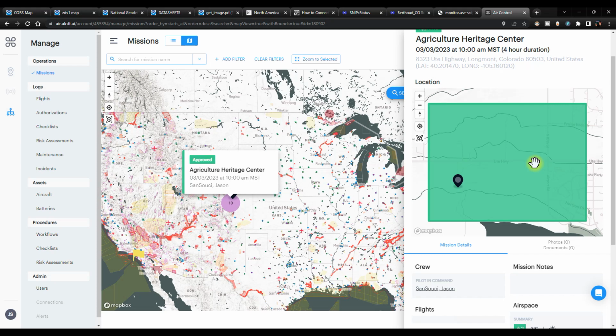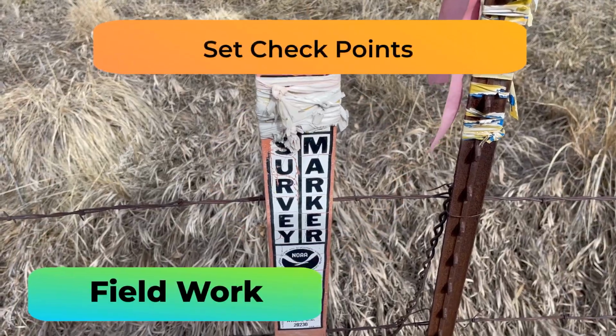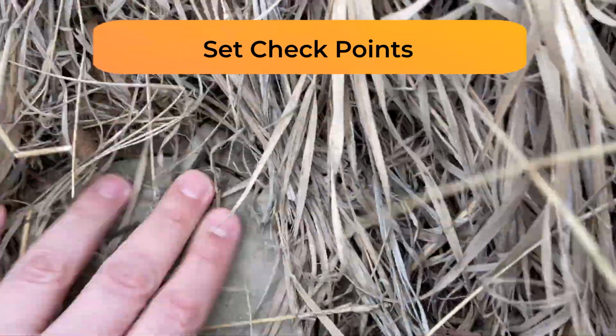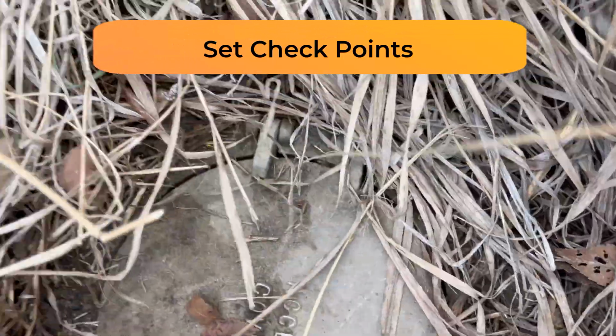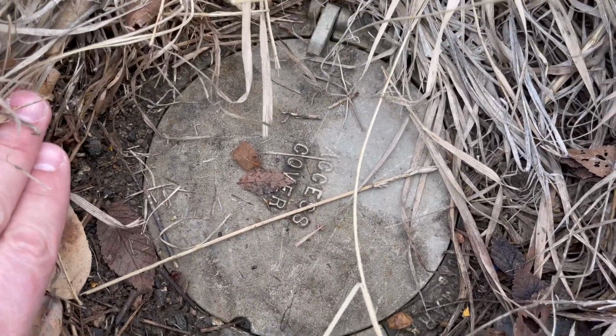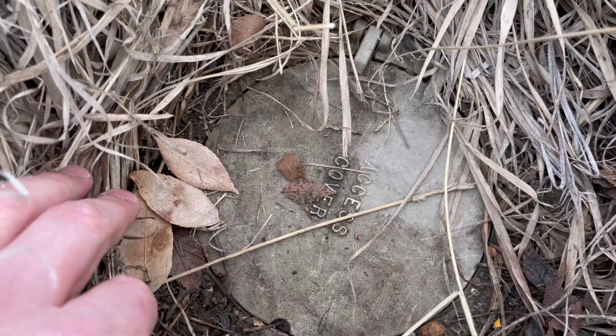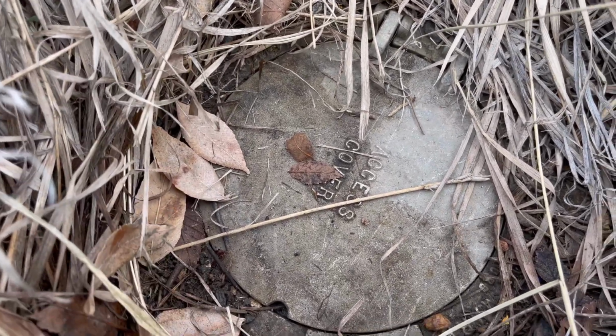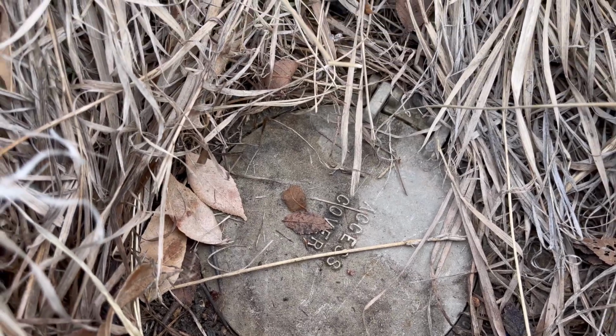The first stop we're going to make is at this NGS benchmark to set our checkpoints. This is a National Geodetic Survey marker. If we come down to the bottom, we can see that there is a cap here. There's a covered access, and within this access, there is the ground control point. So we're going to set our ground control point right here on this spot. We're going to clear a little bit out, and we're going to set it here. Then this is going to be used as a checkpoint for our survey.